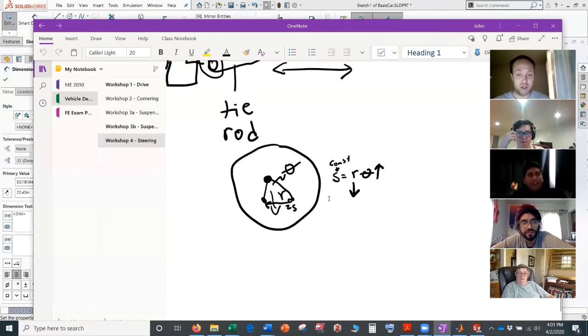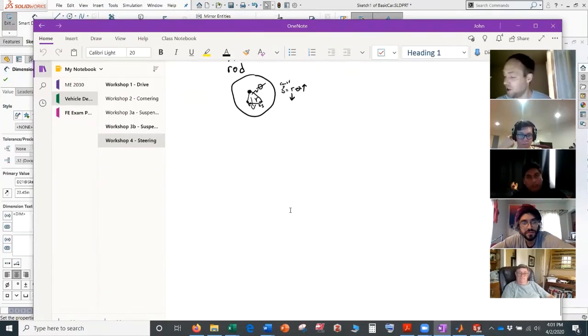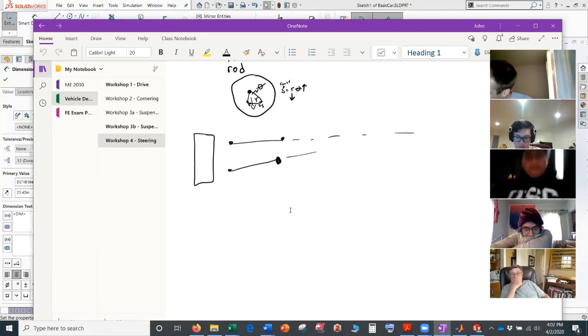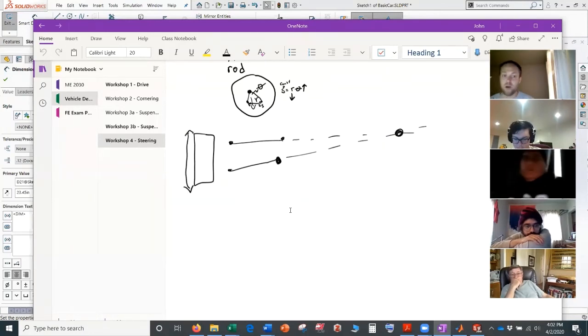So there's one other constraint we haven't been dealing with. If we look at the tire from the back, here's our lower control arm mounting points, and our upper, I should make them a little bit more converging. Right? So we know we can extend these out to get to our instant center. This is kind of the hypothetical point about which our tire will move.